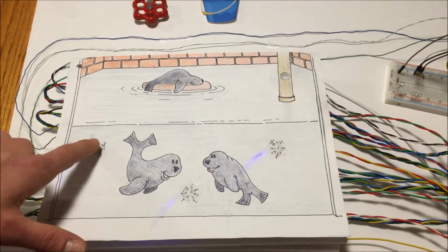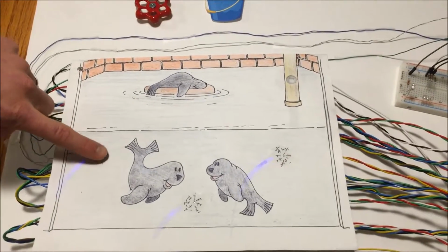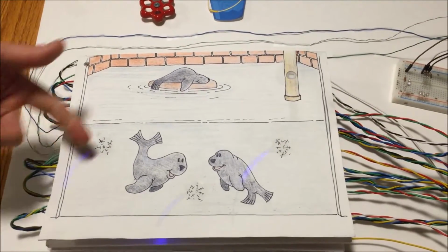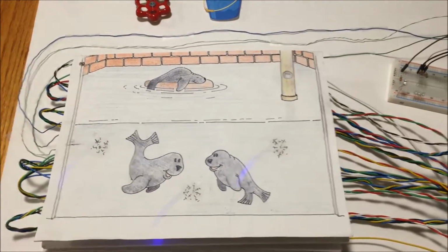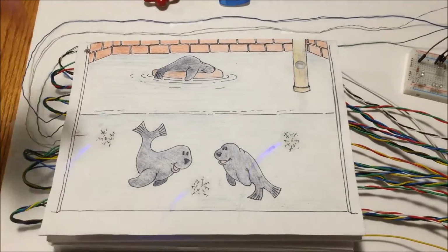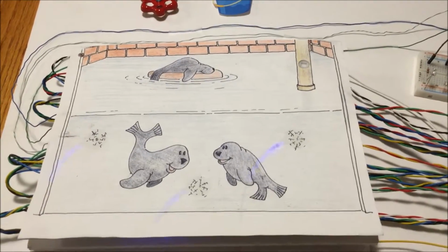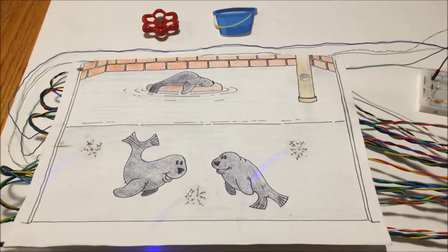So you can see these leaks are controlled. You can plug a leak by simply touching the page at the point of the leak, and then when you let go, you can see that the water starts to flow again. These are actually just electrodes that are controlled by a capacitive touch sensor, an MPR121, that communicates to the development board, the LPC1768, via I2C protocol.